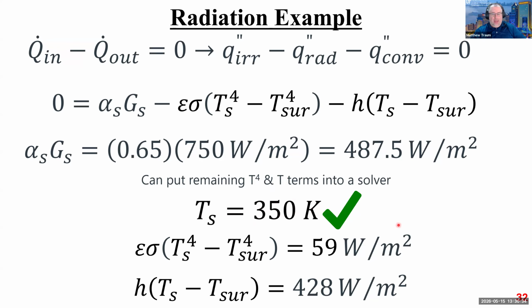Okay. Just sort of as a sanity check, I went back now that I know what the surface temperature is. So two sanity checks. So one, right? Remember all the way back here, we had emissivity of 0.13 around 300 Kelvin. And so is 350 close enough to 300 Kelvin that this emissivity value doesn't change?